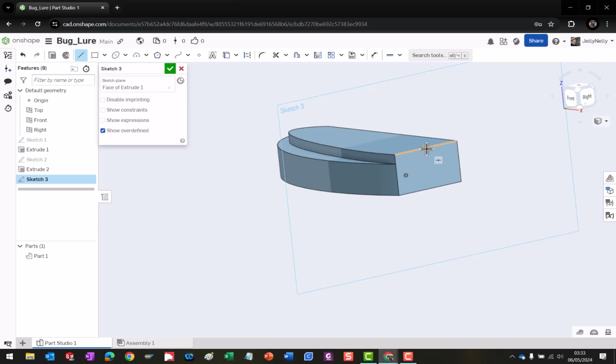So here I'm going to come to the center. Notice that midpoint shows up as a dot in the middle of a little line segment. I'll click once here, drag straight down, and look for that midpoint constraint again. So there we go, and I'll hit escape. And once you notice that line immediately turns black, that's because it's fully constrained. If this point is in the center of this line, and this point is in the center of this line, that line cannot move.